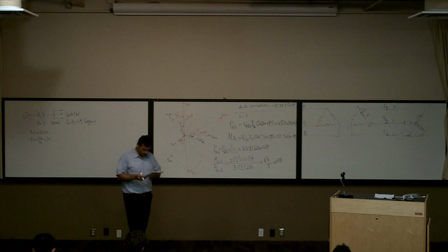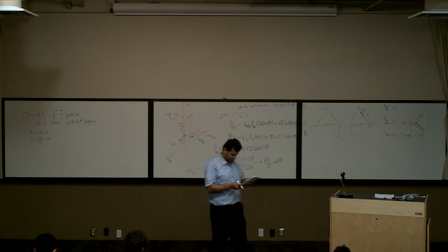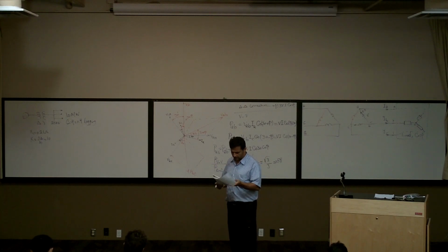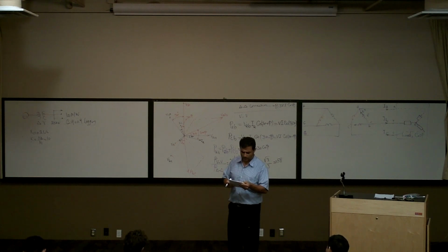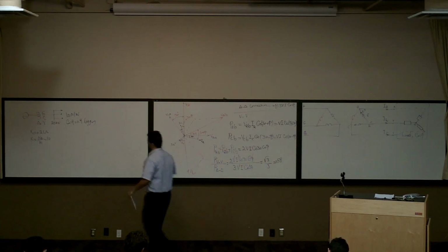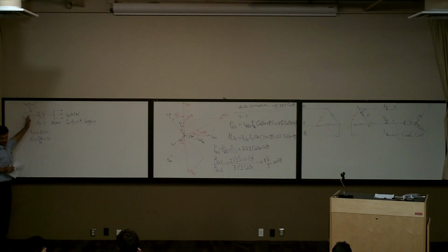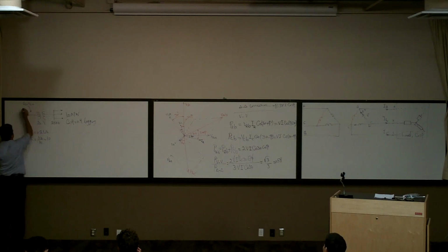So it says substation, you know, 220 kV. You have that one, 220 kV, and now it said find the primary current, primary voltage line to line. Now see, if you look here, I want to know IL, VLL here. I want it for this side. This is the primary. I want to find the primary current, primary voltage line to line, and three-phase complex power here. I want to know the SG.